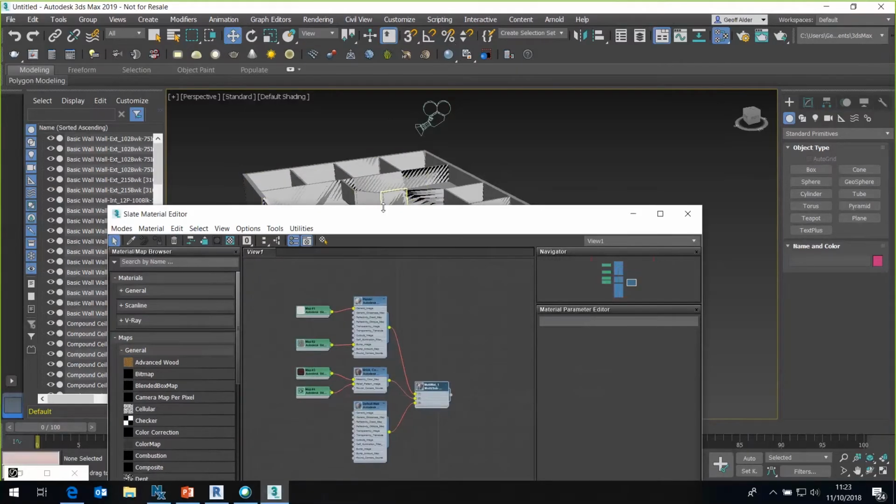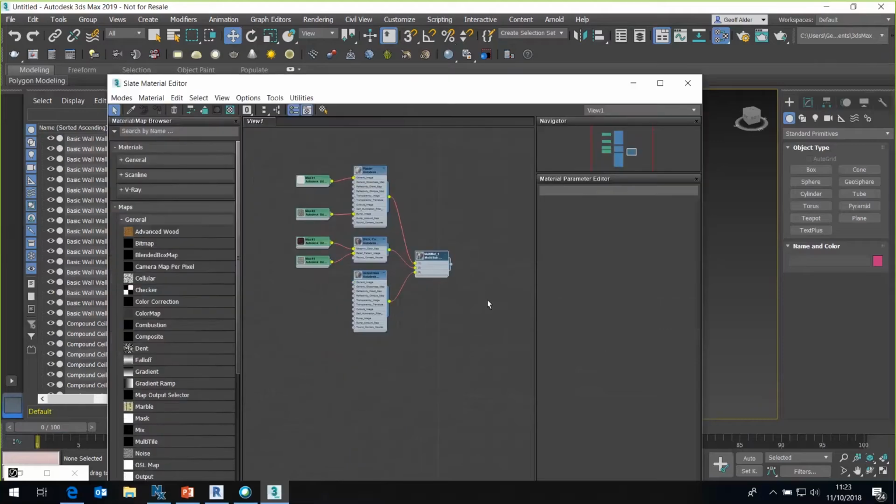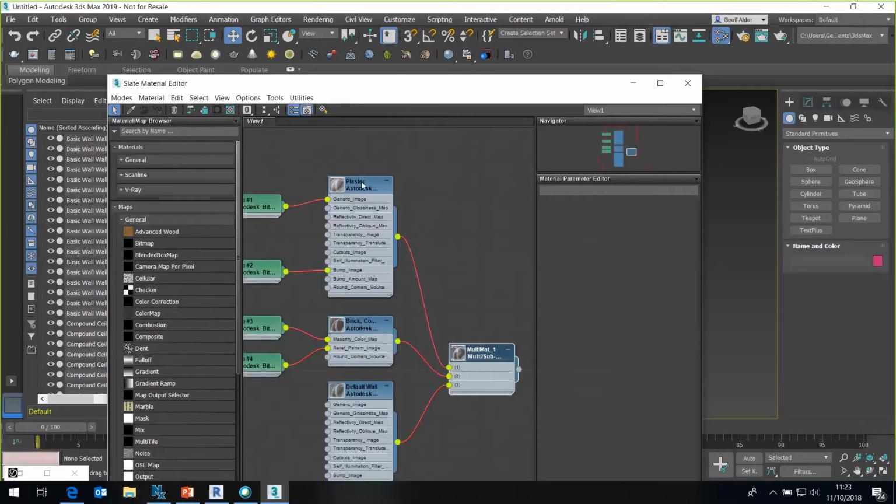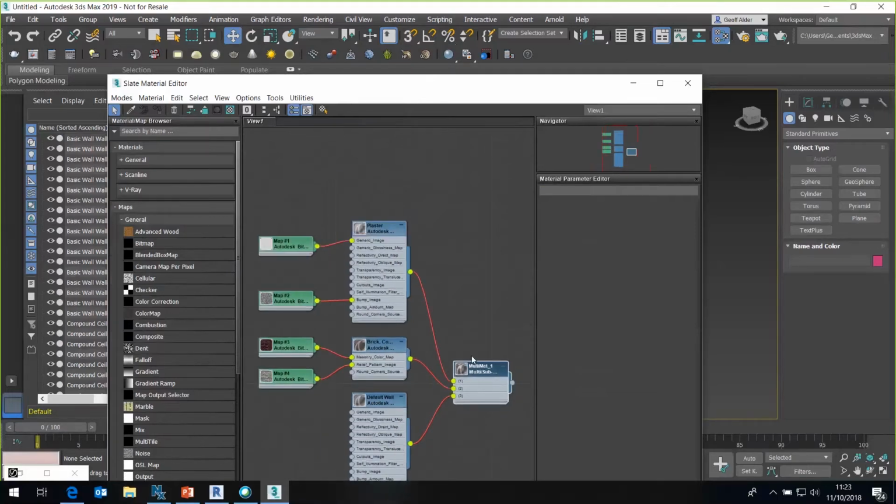So in other words, I haven't optimized the wall, and because the Revit model was not optimized, it will bring in a lot of information that we don't necessarily need for our interior design. For example, this particular wall, whilst I've got plaster here and brick and the default interior, is actually using 3 multi-sub objects. We don't necessarily need all of that to come in.